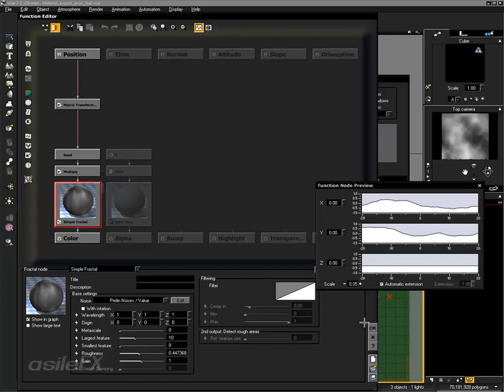If it's above 1, you need to turn down the gain. If it is a more complex function, you need to take that output and add a filter to reduce the gain amount to make sure it is under 1. That will properly map the black and white correctly.